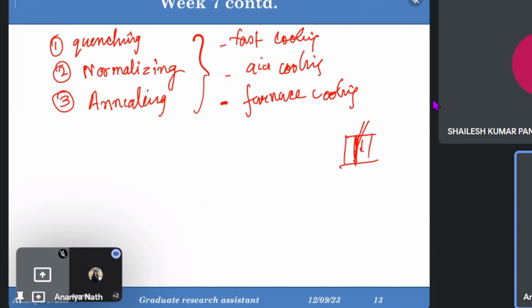This is called nucleation, but there is no growth of the nuclei. They cannot find a preferred site to sit and grow. They will just nucleate and form the grain in the position they were in the liquid state. So there is nucleation, but no growth. You can say that homogeneous nucleation will take place. Homogeneous nucleation doesn't require any preferential site, but heterogeneous does. For heterogeneous, they need to find a preferential site, but for homogeneous, they do not.